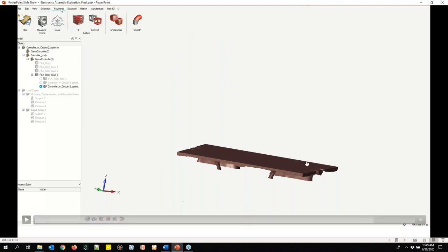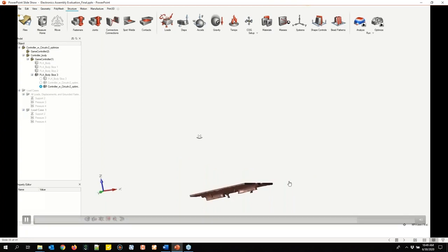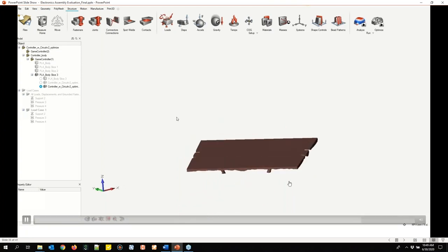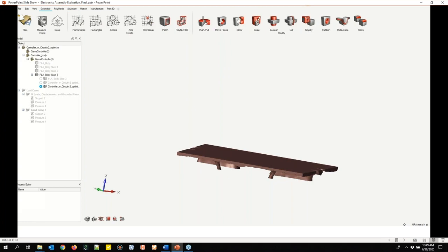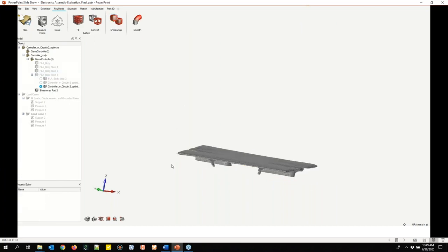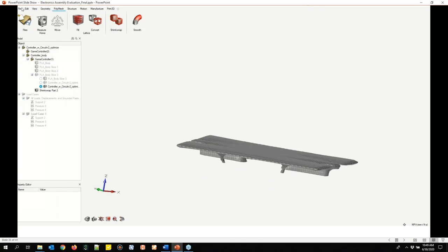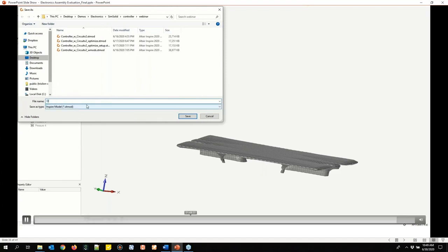We can see that this design is essentially an I-beam. And we know that this makes a lot of engineering sense because the type of analysis we're running has a lot of bending to it. So we know that in a bending cantilever beam, for example, an I-beam is probably the best type of design to address those bending stresses. So in this design generation, it did give us an I-beam without us telling it to make that shape. We basically just said, here's a design space, come up with the best design possible to achieve that engineering objective. So we were able to do that.